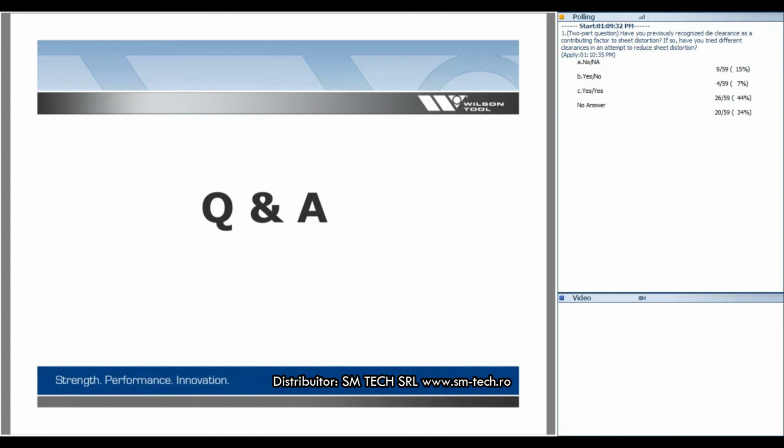I would say it really depends on the forming. When is it fracturing? So say I need to go 300 thou high on end form, but it's tearing at the 250, 200 height. That's when I start invoking pinching, somewhere around there or before there. So it's more of a what failed, identify where it failed, and then make sure we invoke pinching prior to that. So there's no real hard number.